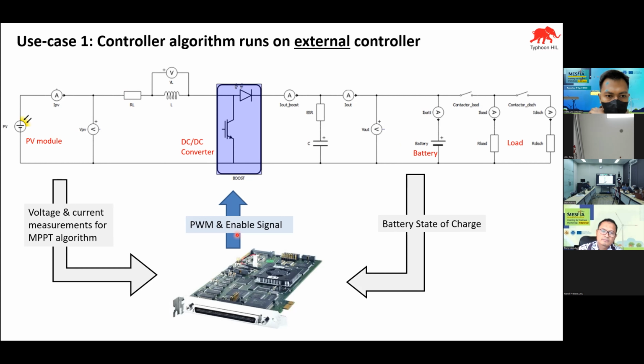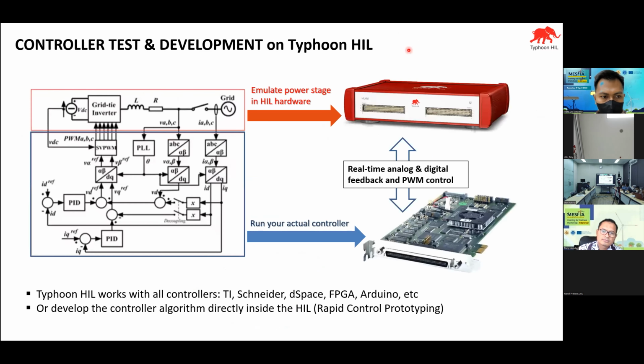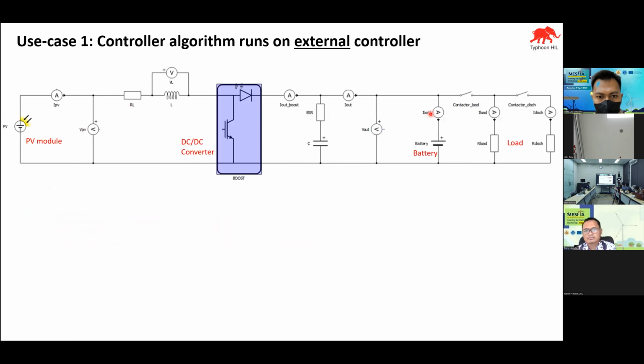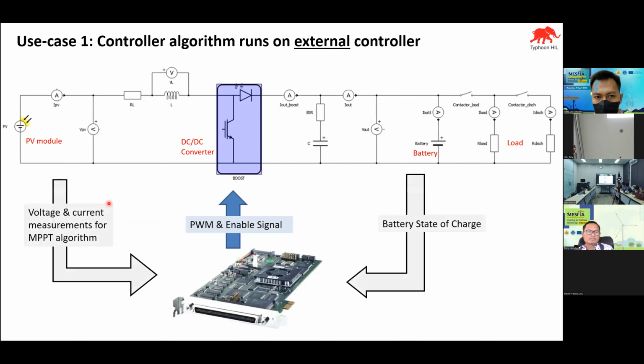All these measurements and the PWM are sent through the input and output ports here. So in that case, you are able to perform a closed loop simulation. Actually, it is not a simulation, it's a real-time test with your actual hardware.